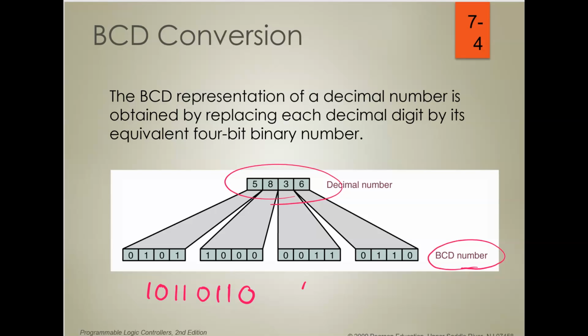My question is, can I consider this as a binary coded decimal number or not? The answer is that I have to partition them into groups of 4. So if I partition them, then I have this one and this one. So it means that this number is a correct binary coded decimal because I have 2 4-digit groups, and each one can represent 1.